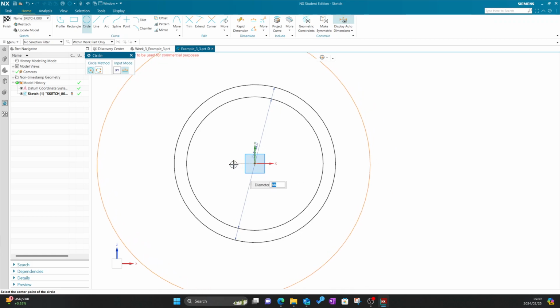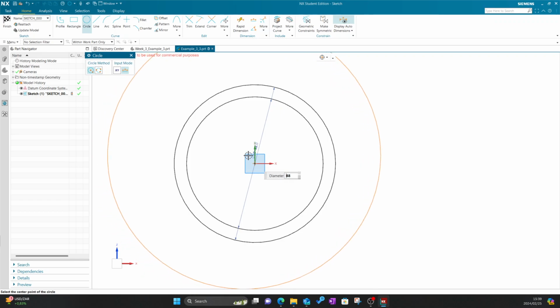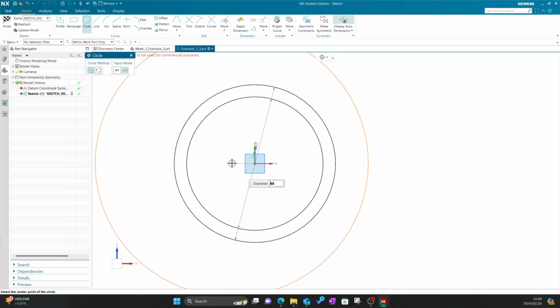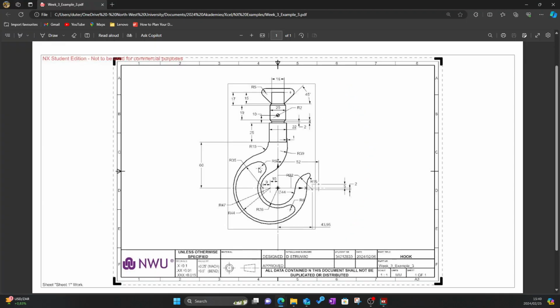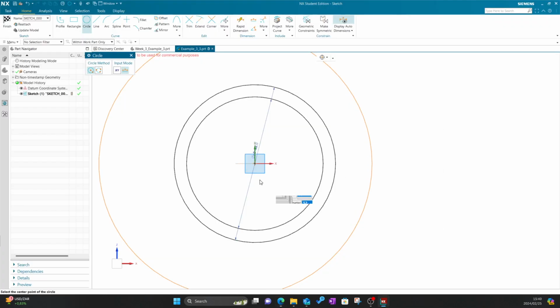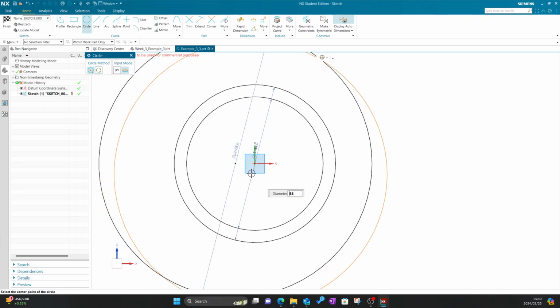So you just drag, if you take it too far above or below, that dotted line disappears, meaning that you're not in vertical, coincident or parallel with that center point's vertical. So yeah, you click a bit left, ensuring it is on a vertical line, which it is for the circle, and just a bit to the left, but that's not 10 millimeters yet.